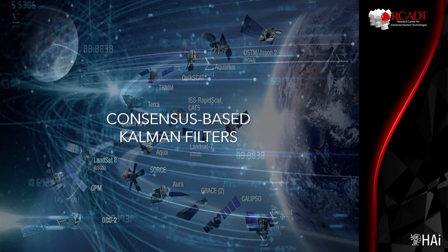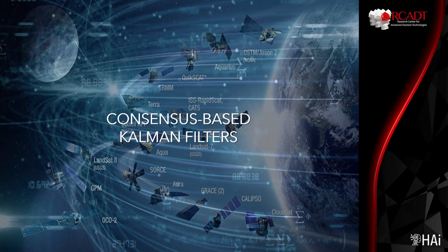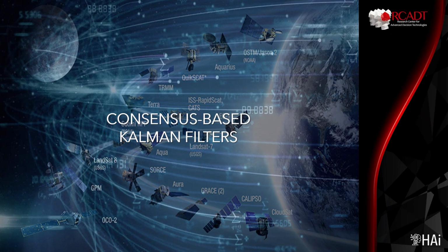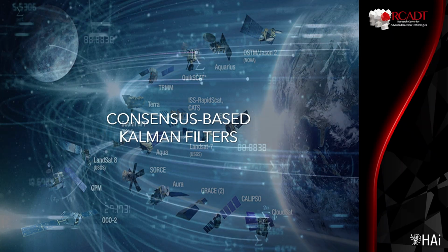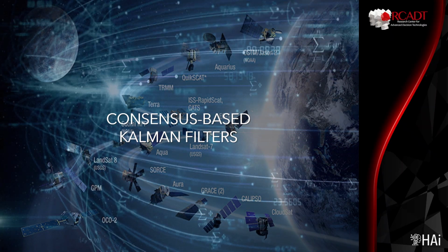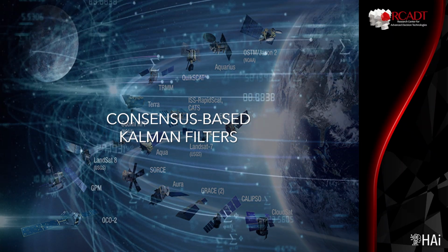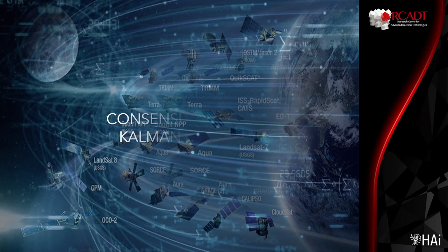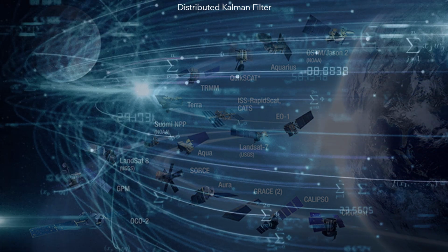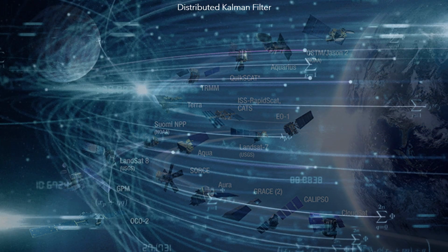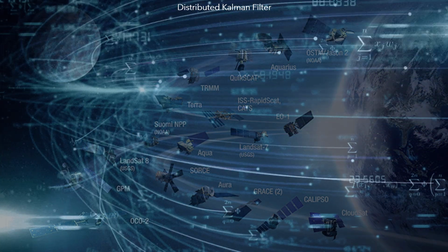Consensus-based Kalman filters. Distributed sensor fusion in sensor networks is one of the most recent applications of consensus problems. It is done by applying different problems that require implementing a KF called average consensus problems. It should be noted that there is more than one way to perform information fusion, which is part of the design of the distributed processing system. Efforts to decentralize the Kalman filter were initiated with the work of Olfati-Saber and Becky, 2002. They decentralized the discrete time Kalman filter for linearized state propagation and measurement equations.